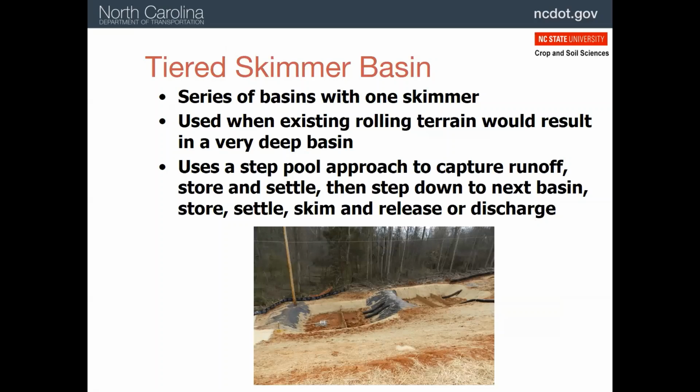When the terrain is very steep, installing a large basin would create a very high bank at the uphill side. So instead, we install a series of basins that are connected to each other.